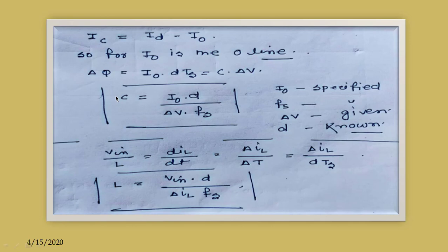Now my intention is to determine, just like in the buck converter, the value of Lmax or Lmin, and what we have mentioned earlier, that when we get the value of Lmax, the duty cycle will be minimum, that is Lmax for Dmin value and Lmin for Dmax value.